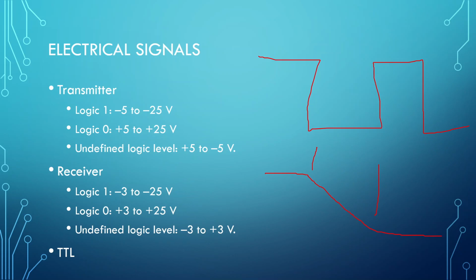If you're starting to get into the new world of microcontrollers, like ESPs, those are only 3 volt devices. So when you're trying to do a serial communication with it, it's only a 3 volt signal, not a 5 volt signal. And if you're trying to do something right from your CPU to CPU, like on board, it's only like 1.2 volts. So our voltages kind of keep coming down over time. Originally, I was really annoyed by the whole different voltage thing, but it's just something you've got to deal with.